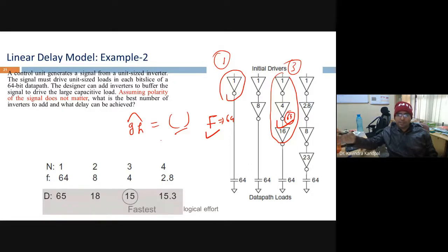If the load is high, then instead of making W by L of this particular inverter very high, because usually students think that making W by L infinitely high means the current driving capacity will increase very high, right or not? You all say current is proportional to W by L. If you increase the W by L, the current will be higher. If the current is higher, the load can charge and discharge very fast. Yes or no? This is our assumption.